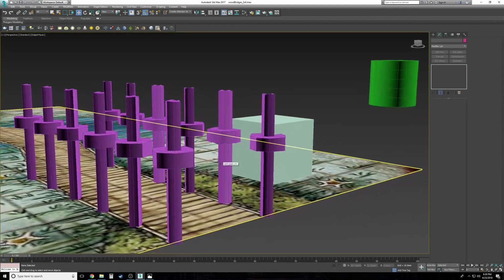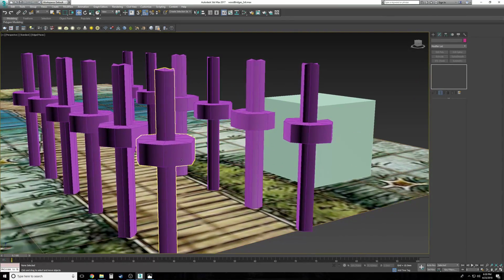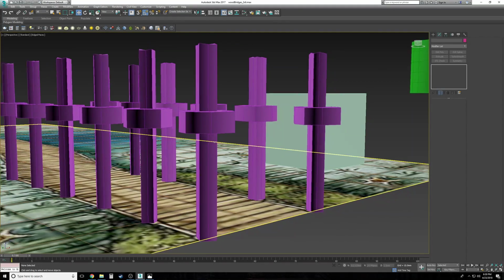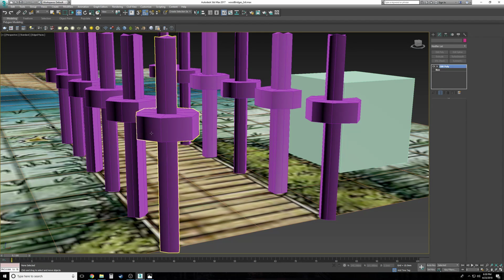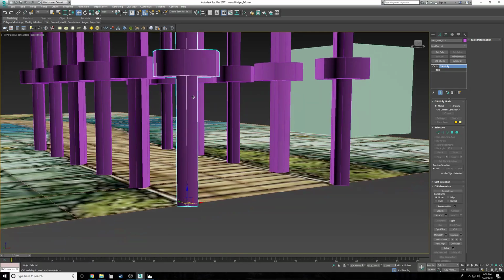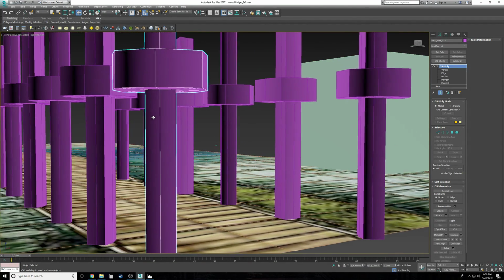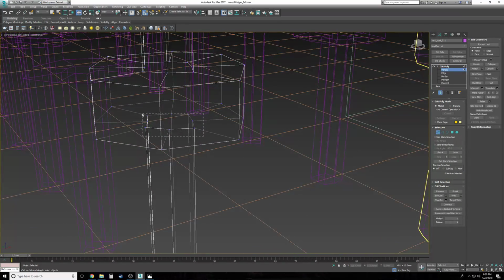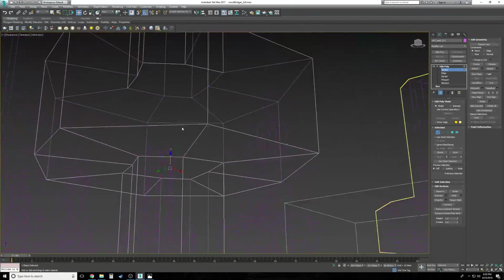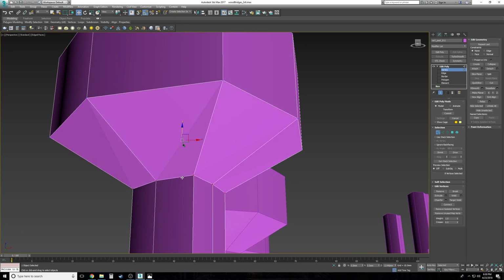Now that we've got the base here, that will basically just hold it up. It doesn't really matter, we can adjust that thickness later if we want to. Right now, it's good where it is. I want to make this, however, right now it has a huge overhang, and that's not great because overhangs make bad printing. So we're going to select just the inside part of the bottom part of this piece right there, and we're going to bring it down.